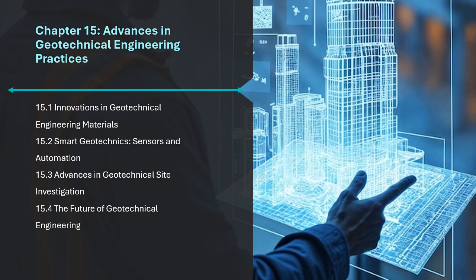Dynamic Cone Penetrometer (DCP). The Dynamic Cone Penetrometer (DCP) is a portable tool used to measure the strength and stiffness of soils, particularly in areas where other methods like SPT are impractical. It consists of a cone attached to a rod, which is driven into the soil using a hammer. The depth of penetration per blow is recorded to determine the soil's resistance to penetration.